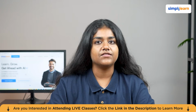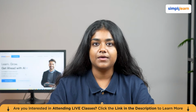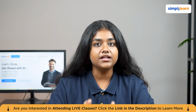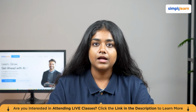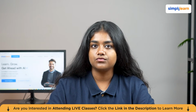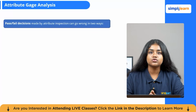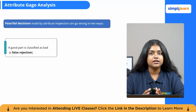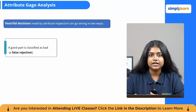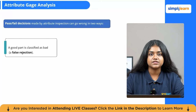Attribute gauges are used everywhere. Incoming inspection of visual features, surface finish assessment, color matching, defect classification. In many industries, attribute inspection is the primary type of quality control used. But attribute systems have their own sources of error and they require their own analysis methods. Attribute inspection is used when the result is a category and not a measured number. Examples include pass or fail, good or bad, present or missing, or acceptable or not acceptable decisions. Since the inspector is making a judgment, the inspection system must be checked for consistency and accuracy.